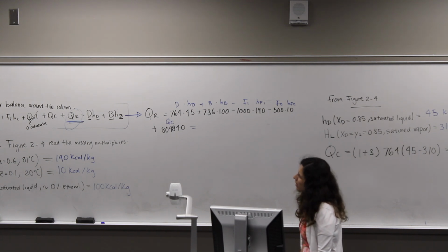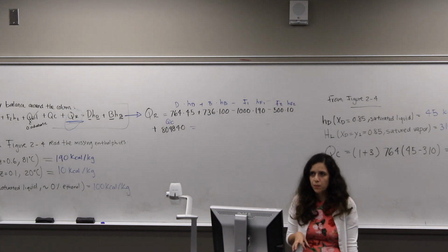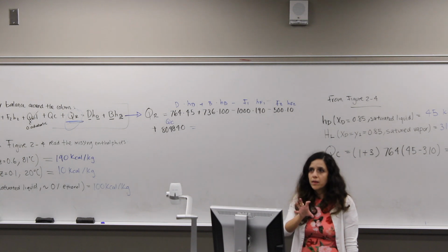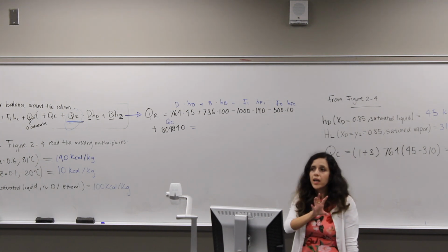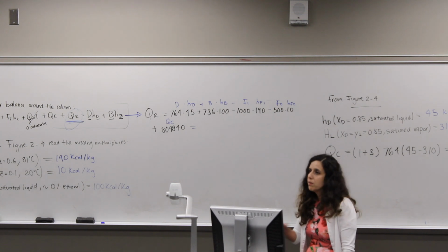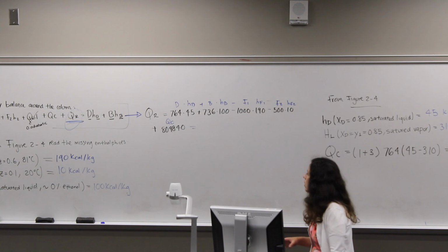So this procedure is kind of a standard, guys. It's what I want you to visualize, and maybe the next problem I will let you do alone. General mass balance, then the balance for the most volatile component, then just do the balance either on the reboiler or the condenser and move to the general mass energy balance. And that completely specifies your column in terms of mass and heat loads.